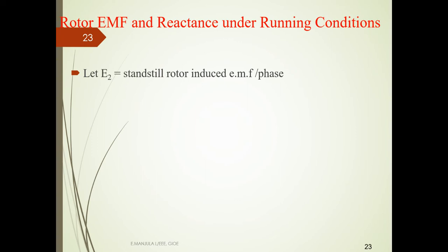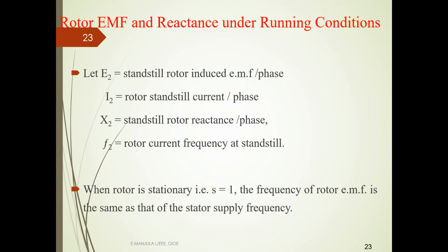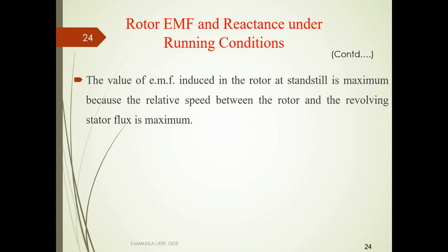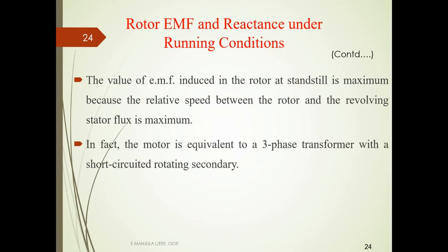Rotating EMF and reactance under the running conditions. So we have discussed this here. When the rotor is stationary, that is S equals 1, the frequency of the rotor EMF is the same as that of the supply frequency. So the EMF induced in the rotor at standstill is maximum because the relative speed between the rotor and the revolving stator flux is maximum.